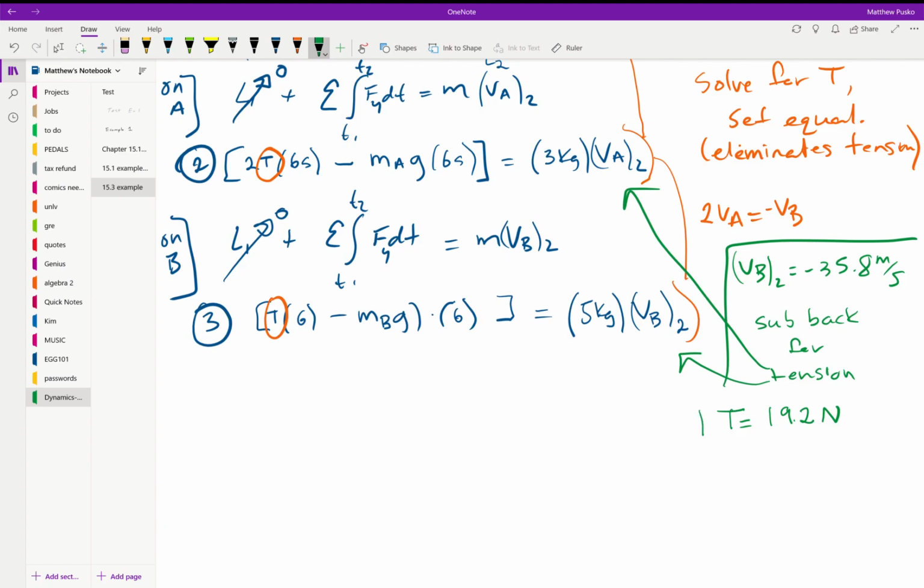That tension is positive, right? We cannot have a negative tension, so it is absolutely a positive tension. If you get a negative answer there, you should check your equations, check the signs on your free body diagram or how you translated those to algebraic equations.